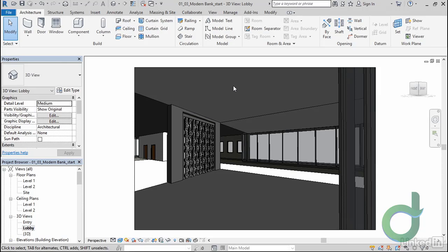If you'd like, you can finish out the rest of the ceiling or simply leave it and progress with the rest of the design. I've finished out my ceilings. We can see that there's the drawing lines here, showing some divisions between them, but they should render fairly smoothly. This is an opportunity again to put in something as a trim line. The original building has reveal channels, maybe an inch square, demarcating different parts of the ceiling and lining up with the columns and the rest of the building grid. So that's an option here, also to reduce the size of these ceiling pieces even further and add in those details. This is your call.